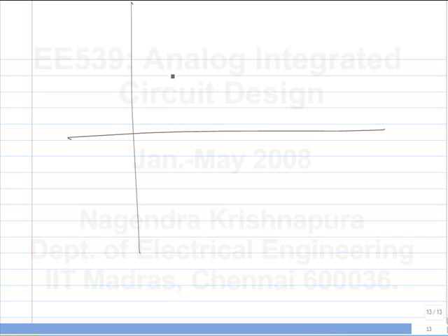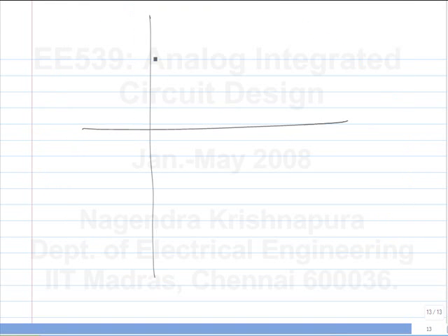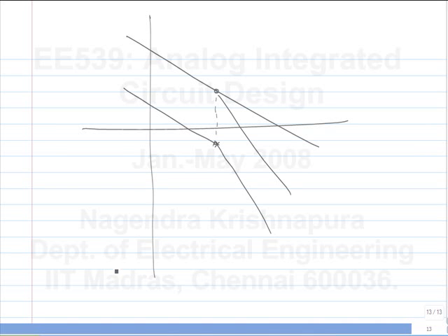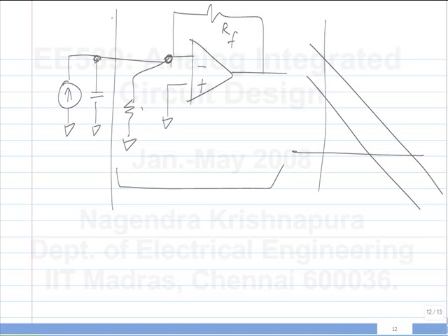So let's say in fact our problem was not like this, right? So our problem was that this was the op amp and the pole was here. Okay. Now, if I push this pole to a point below unity gain, it will work. Okay. So this I can do by introducing an attenuation around the loop. Okay. So by reducing the loop gain. Now that is not the only thing this is doing. Where is the pole frequency? Let me call this Rx. Where is the pole?